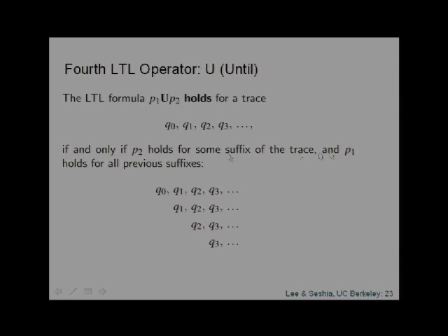Okay, this is also a common way of doing handshaking. Especially in hardware, right? People who design buses have designed protocols where, let's say, a particular core raises a request to access memory, right? And it keeps the request high until it gets a grant. That's a typical pattern that you see in the until case, where some signal p1 must be high, it should be 1 until your request is granted. So this sort of pattern also appears a lot in protocols.